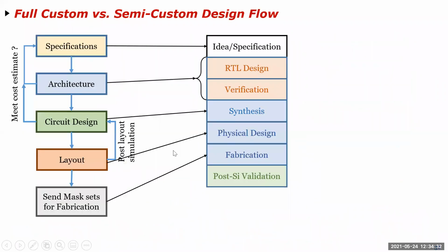Okay, so I just wanted to quickly show that I think a lot of you are asking what's the difference between semi-custom and full custom. So I just made a one-to-one. So specification which you have is obviously the same. The architectural phase which we do in full custom, that's also there actually in semi-custom as well. So where you're doing your RTL design and verifying, so that could be these two steps. Circuit design is what is a part of synthesis, and like as I said, one is not more accurate than the other.